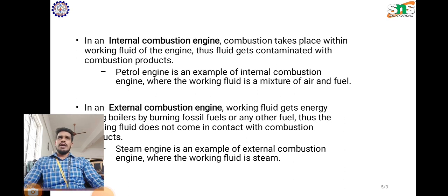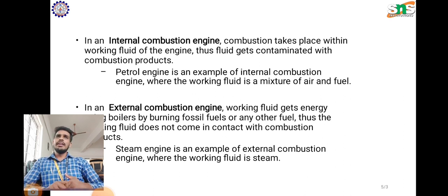Then IC engine: the engine working fluid becomes contaminated with combustion products as a result of combustion occurring within it. Example: an internal combustion engine is a petrol engine which runs on a fuel and air mixture. In an external combustion engine, EC engine, burning fuel or any other fuel in boilers provides energy for the working fluid. As a result, the working fluid is kept away from combustion products. Example: an external combustion engine using steam as a working fluid is the steam engine.